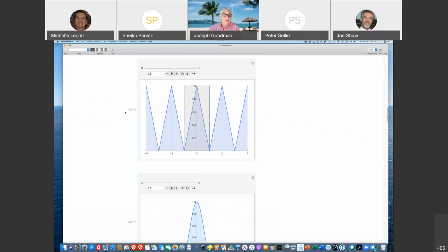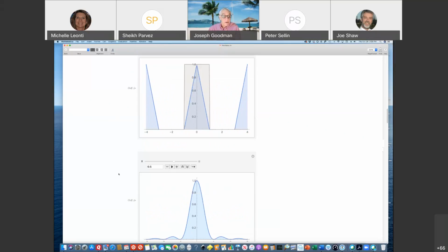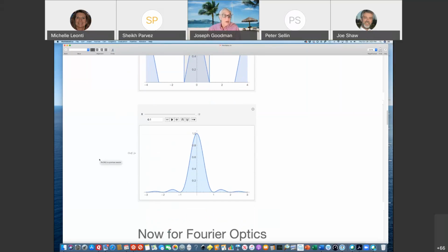And as we lower the sample spacing further and further, the spectral islands move further and further apart, and we continue then to have proper sampling of the sinc squared function, and the central island of the spectrum is being filtered out under all of these conditions.